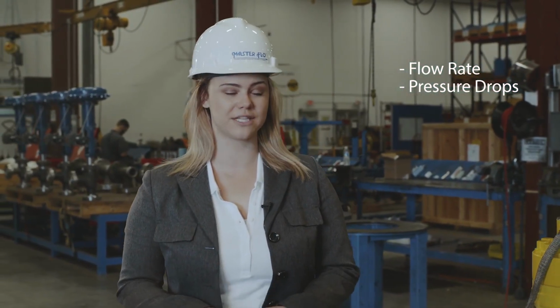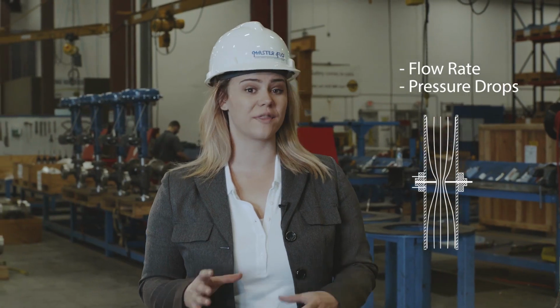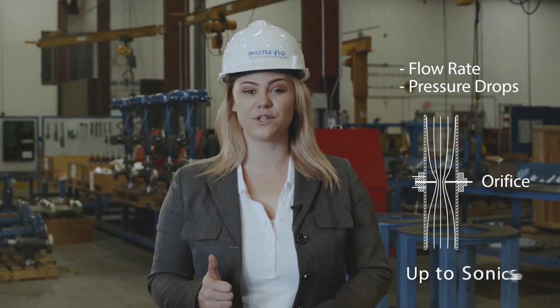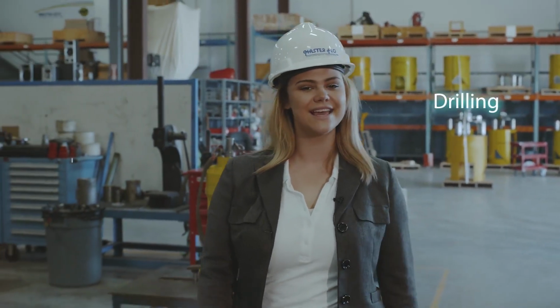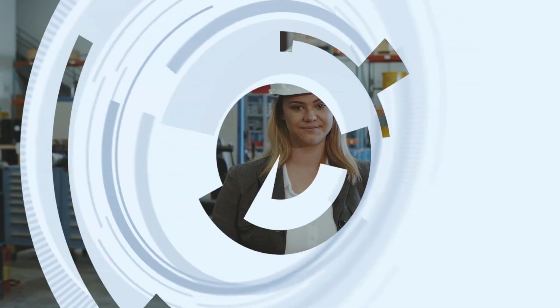Choke valves are used to control flow rate and pressure drops. Reducing the flow channel with an orifice accelerates fluids, sometimes to sonic speeds. For that reason, the design of a choke valve must consider the effects of erosion, high fluid velocity, and significant pressure changes. Choke valves are categorized by their application, including drilling, injection, and production.